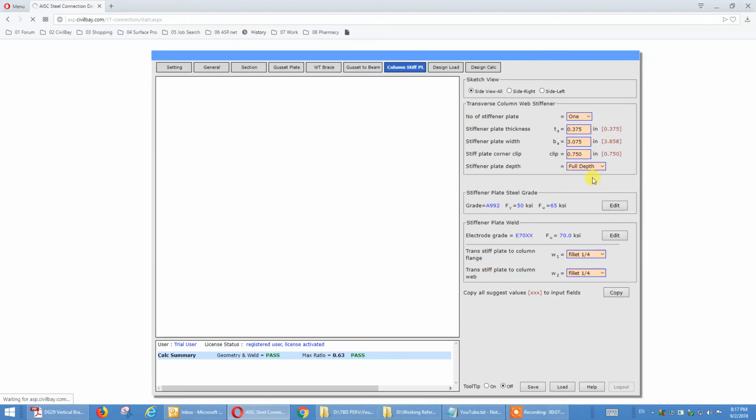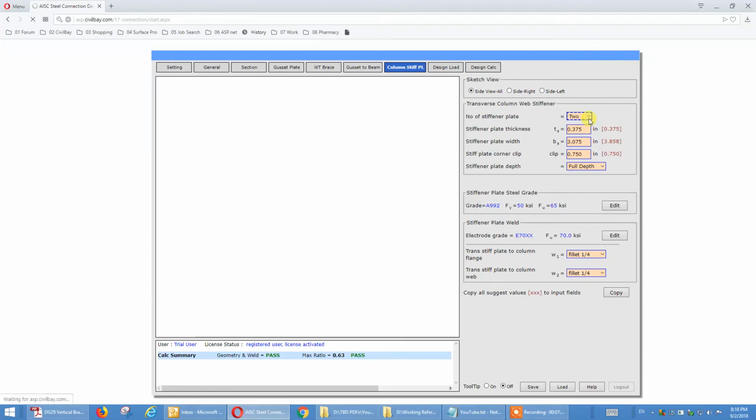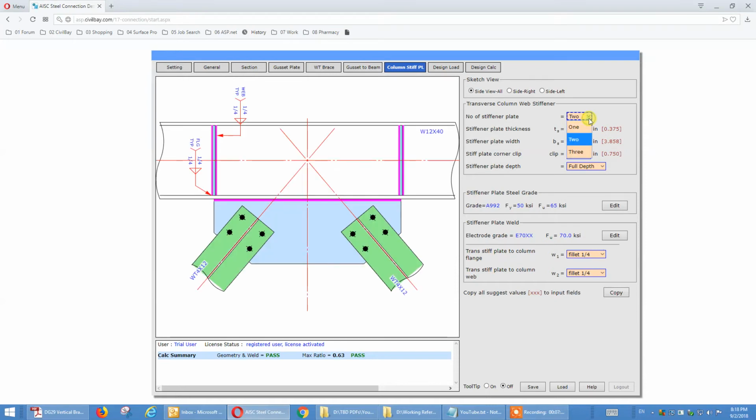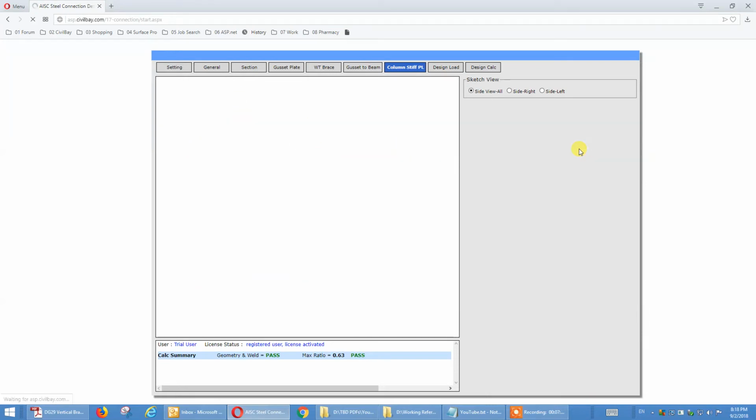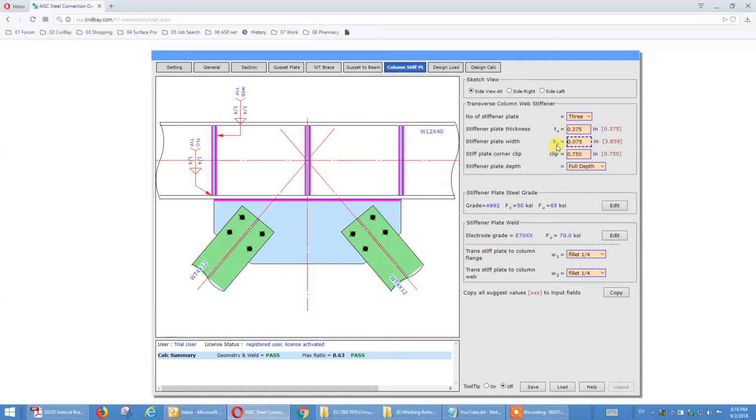So when you have large axial load, it's required. I put stiffeners in terms of Chevron, like 2 or 1, or you can get 3. I have 3 options here. We normally put stiffeners on, 3 stiffener plates like this. That's cost. I know labor cost in North America for welding this stiffener plate, cutting, welding, is very high.